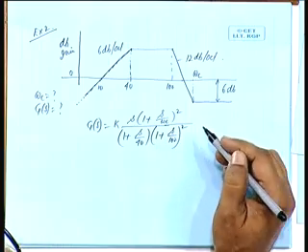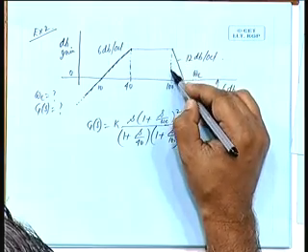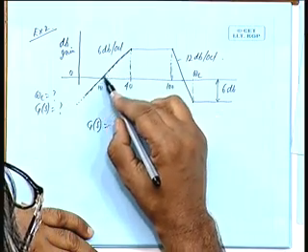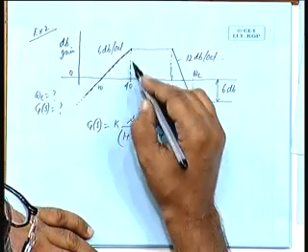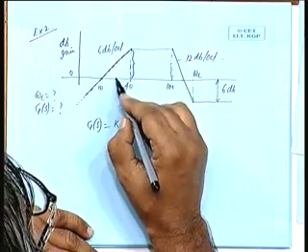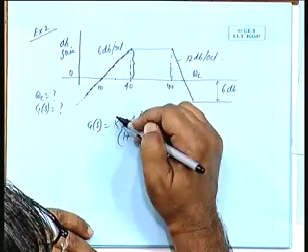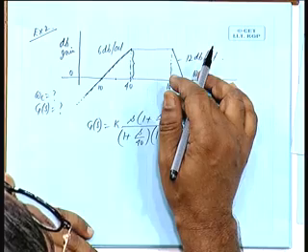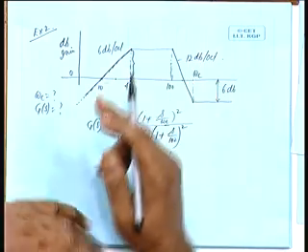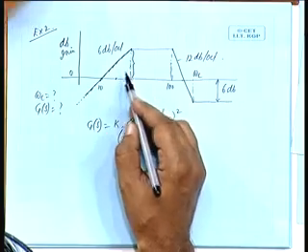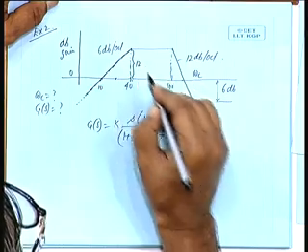Now, what is omega c? From 6 dB per octave, if that is a slope, so from 10 to 40, how much will be this height? 10 to 20, 20 to 40. So, there are 2 octaves. So, it will be 6 plus 6, 12, is it not? 6 dB per octave. If you double it, you get 6 dB increase. So, 10 to 20 it will be 6, 20 to 40 it will be 12, another 6. So, this is 12 dB.